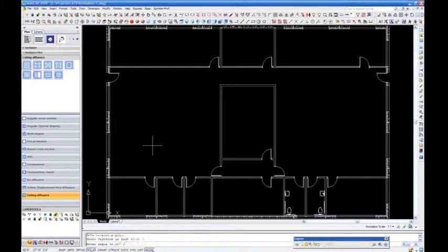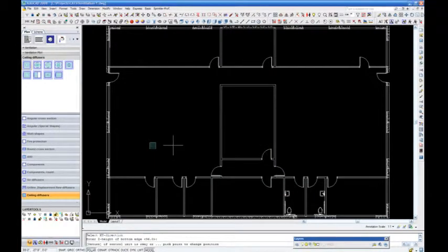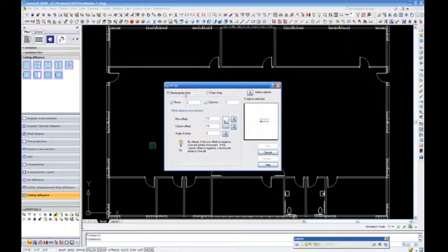The command bar is asking to select Start Point. Next, the command bar is asking for the Z elevation bottom edge. Our elevation height here is 96 inches. The software is asking to select the layer management for all diffusers. Our first diffuser is now placed.